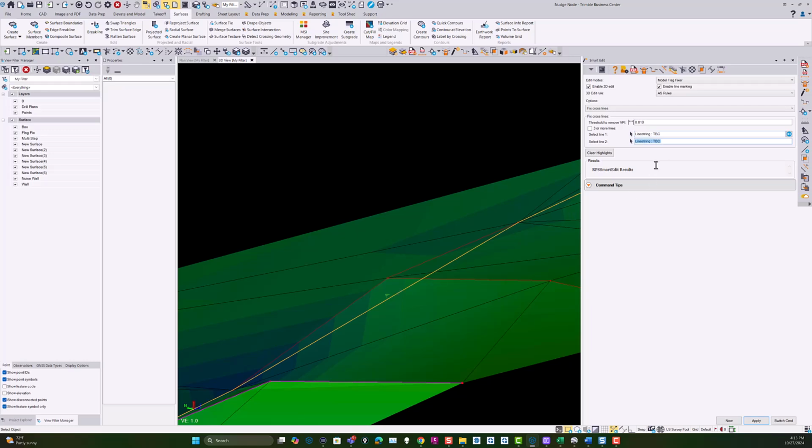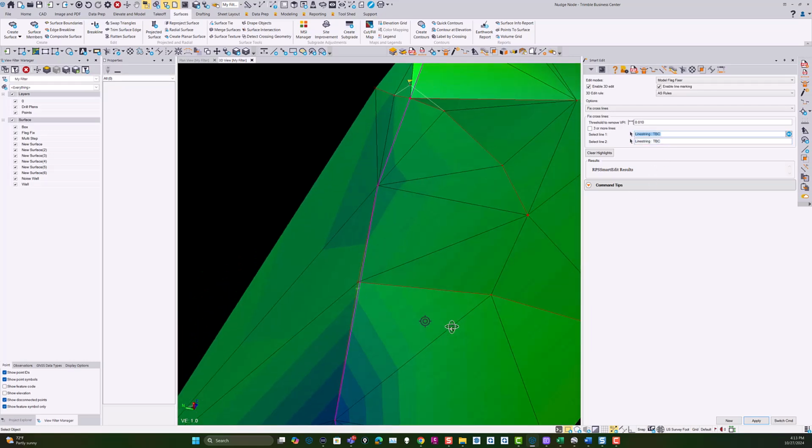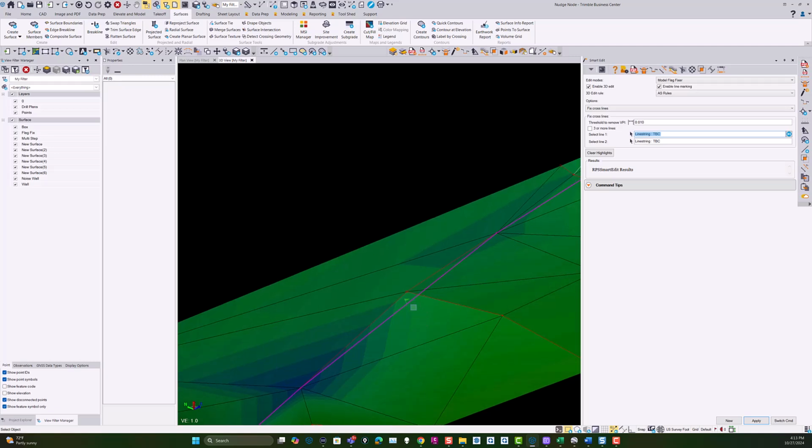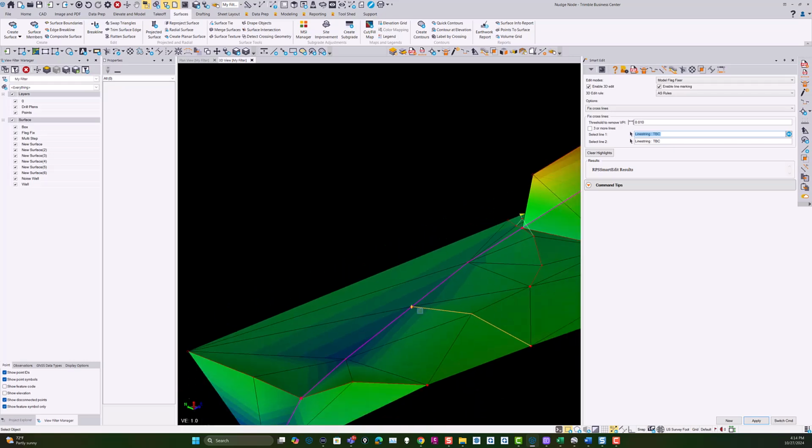In this case, did I pick line 1 there? I didn't pick line 1, right. So pick line 1, pick line 2, and at that point again it gives us the value. So which way around did I pick it now? Let's escape from there, do that one more time. So if I pick line 1 and line 2, and then I want to take the line 1 elevation and say OK, and that will then just drop this one down and fix the elevations.